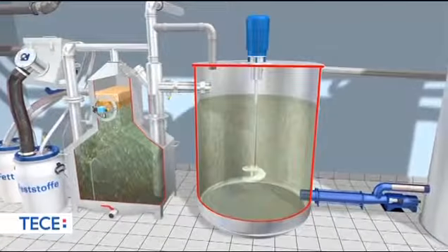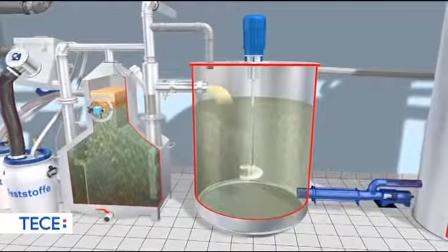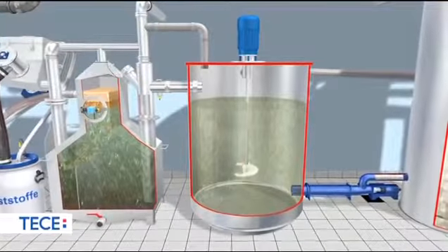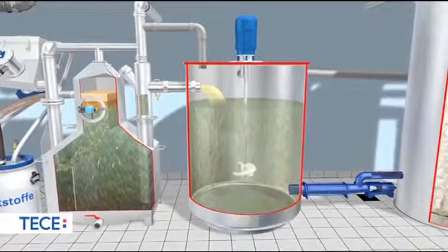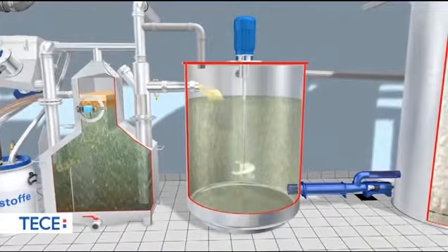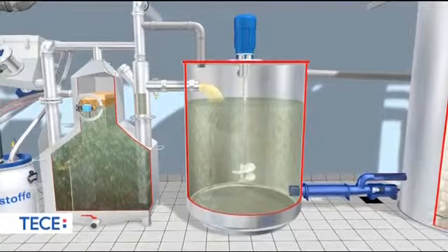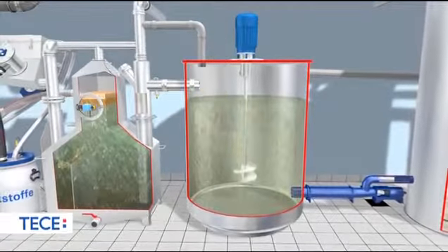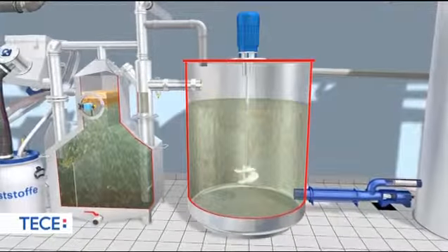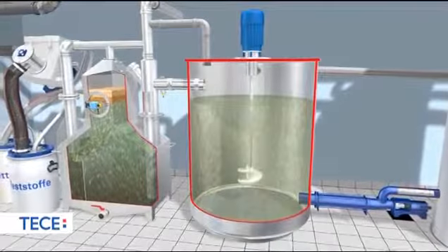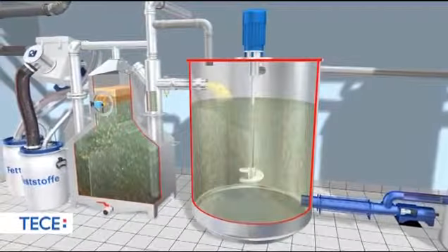During the first step, the discontinuous flow of liquid ensuing from the grease separator is collected in a buffer basin, the so-called integrator. This serves to compensate for any peak loads in the wastewater and thereby prevent overloads in the subsequent treatment steps or any damage to them. An agitator running at a slow speed continuously mixes or homogenizes the wastewater. This results in an even distribution of the substances contained in the wastewater as well as in a uniform temperature.